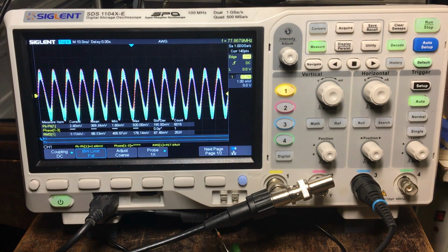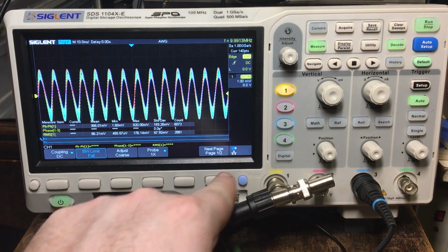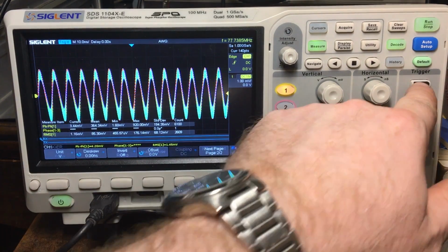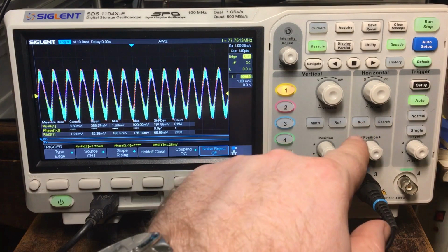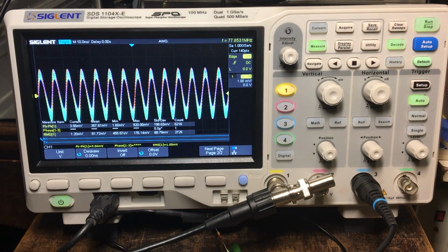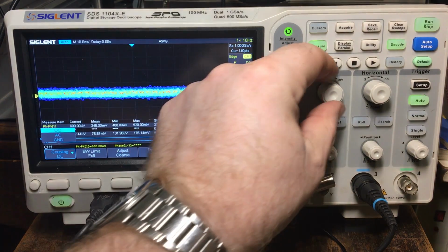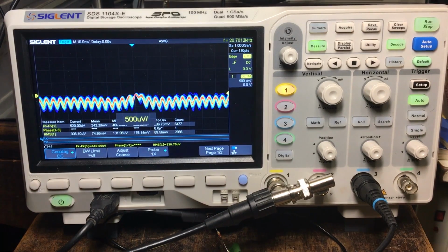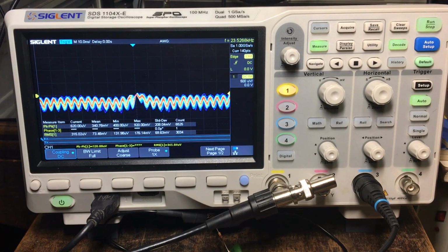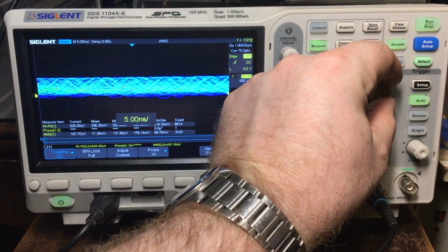But okay, now I did have some bandwidth limiting on here. Noise rejection, I did have that on or off. That's okay. So yeah, it's fine. I think it's what it is. Yep, nothing limited there. 400 megahertz, and yeah, that's just basically unusable down there. Right, no good. That's 200 millivolts input, and it's just no good there.